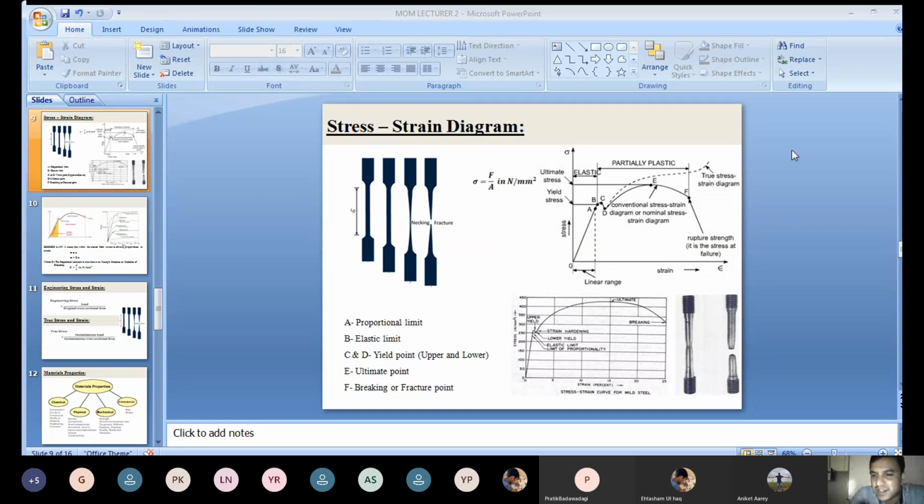And what we can see here, when you conduct the experiment in the material testing lab, is this specimen here. Now, what is the necking formation here, and how the material fails here? If you see the cup and cone shape here, this is the cup and here is the cone shape. Cup and cone shape you will get here. That material is called a ductile material. We will discuss that later. Again, in this graph you can see that both are the same, right? This is with actual values I can show here. Is there any doubt regarding the stress-strain diagram?